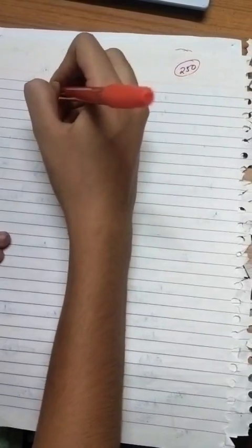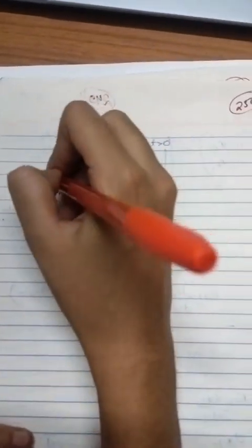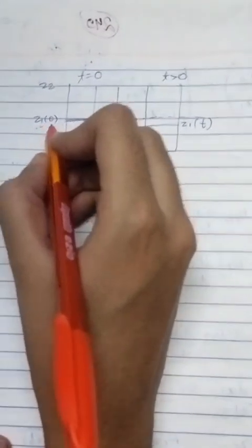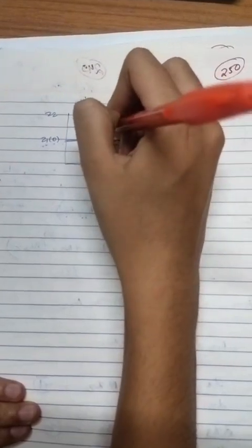So basically what we are saying is that this is our tube and this was the liquid level initially, at time t equals 0. After some time, at time t greater than 0, the liquid level would change, and this is denoted by z1. The change is h of t, and z2 is this. Z2 would remain constant, only z1 is changing. This is z10 denoting the initial value of z1, and this is z1t denoting the final value of z1, and this would be our value of capital H.